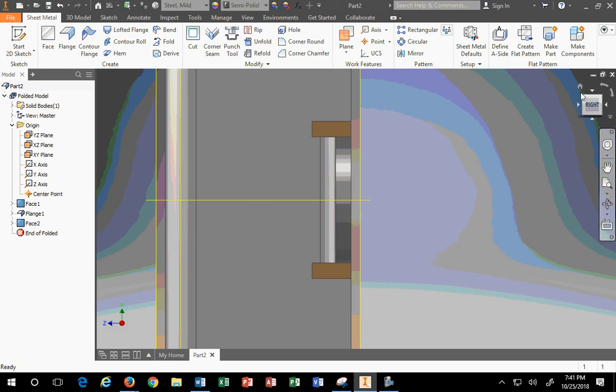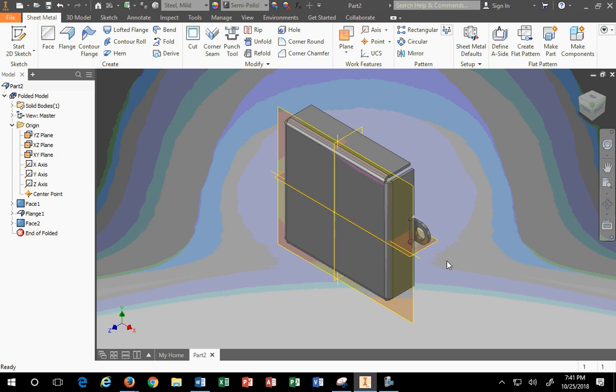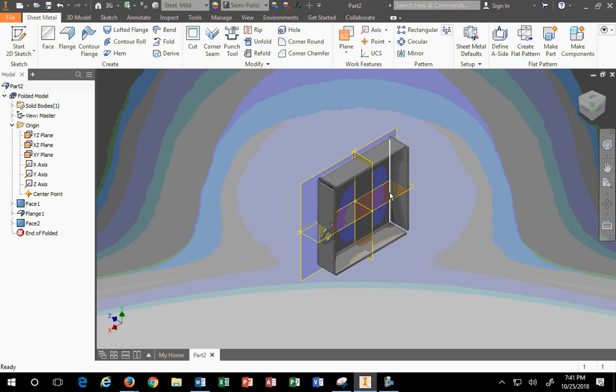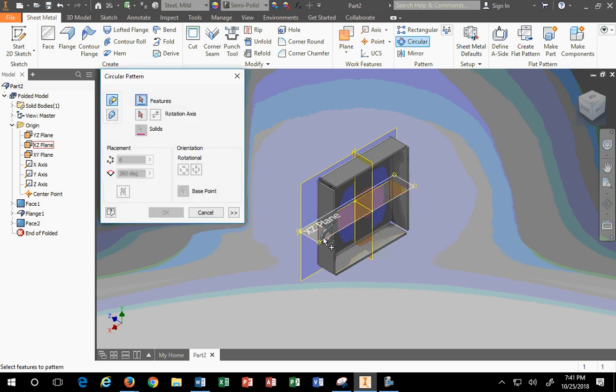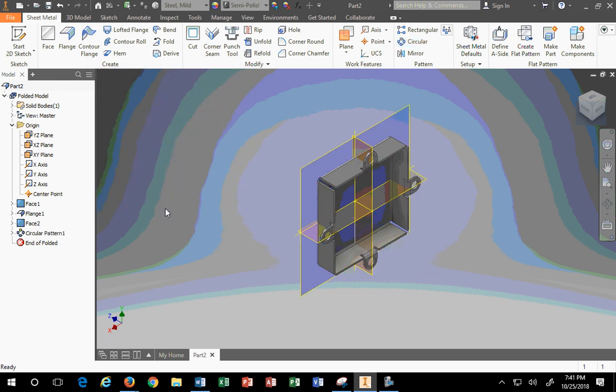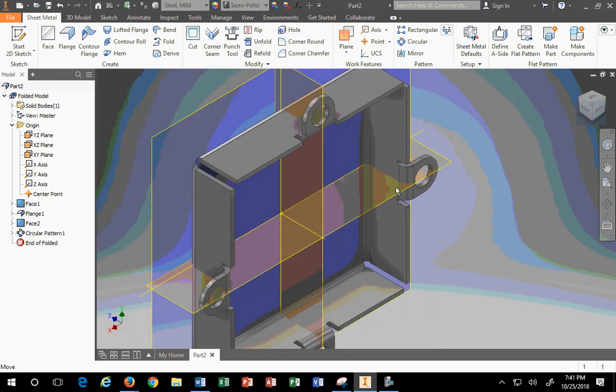Now, being who I am, I've got one down. Do I really want to redo that activity 3 more times so I can get 4? What do you think I should do? Circular pattern. Oh yeah. Circular pattern, that's my feature. My rotation axis is this center. I need how many total in the end? 4. I hit OK. Done. And if you're freaking out thinking, oh my God, will it actually do everything? The answer is yes.